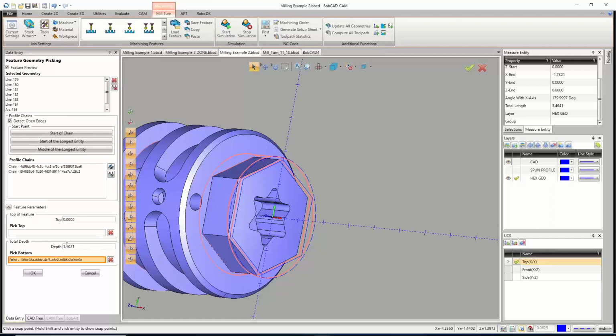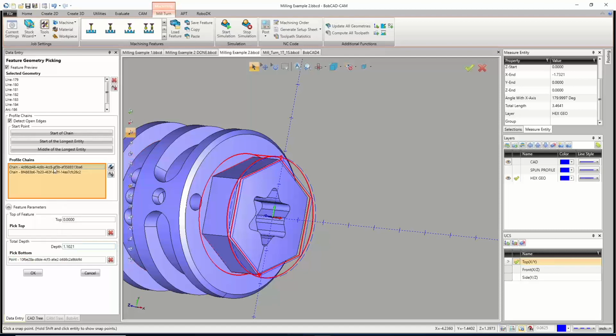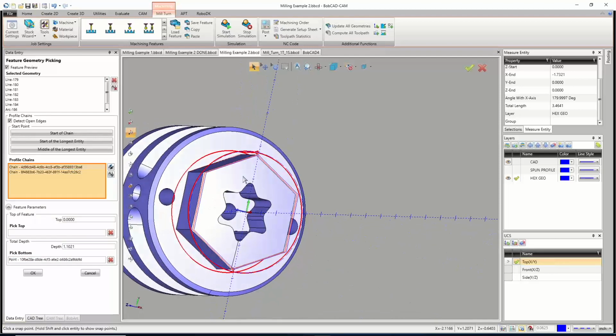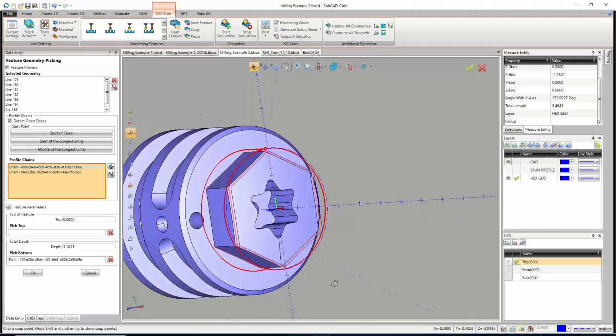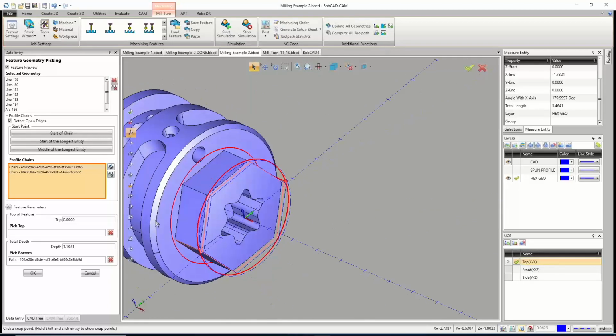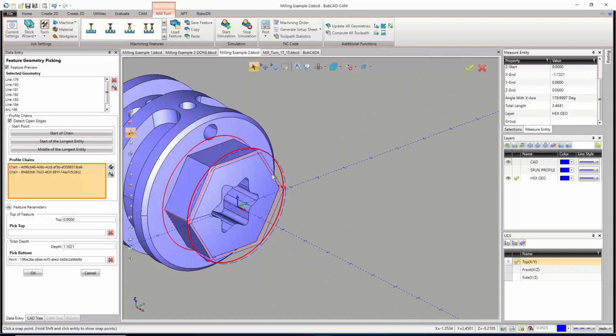So the only change I want to make now is I'm going to do my leads for my inner chain there. I want them in the middle along my X if I can help it, right over there. We could also go right on that. Let's go on that corner. We'll set them on that corner. Actually, no, we'll go right there because I have right angle leads currently. So we'll try that. So hit OK.